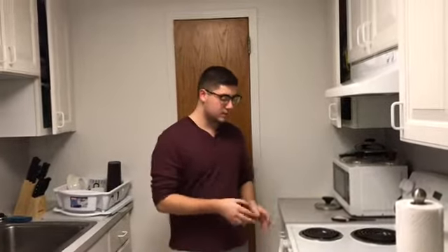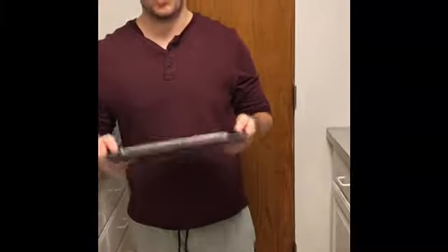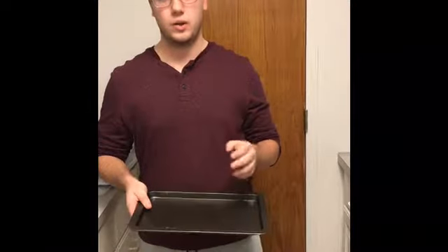Now for an oven, T infinity would be the temperature we set it at, and for us we're going to set it at 200 degrees Celsius. And the temperature of the surface would just be ambient temperature, which we're going to take as 25 degrees Celsius. So the units for convection are watts when you use area, and watts per meter squared when you don't include area in the equation.